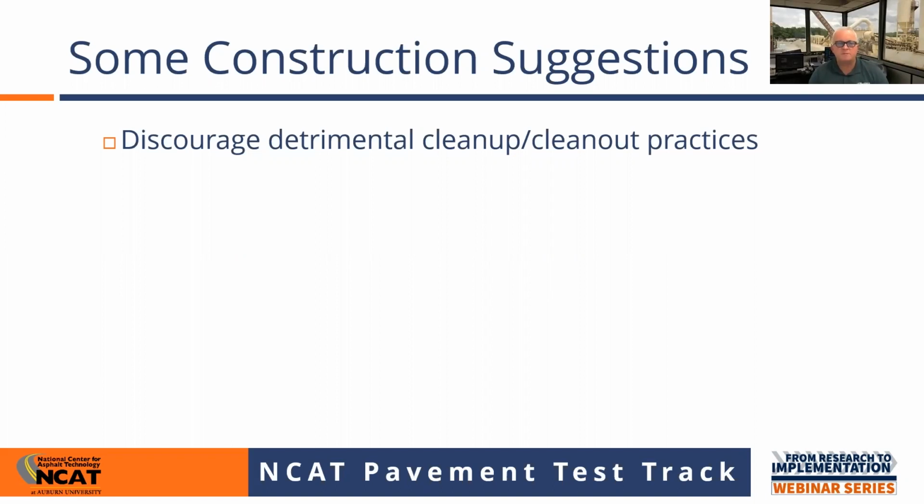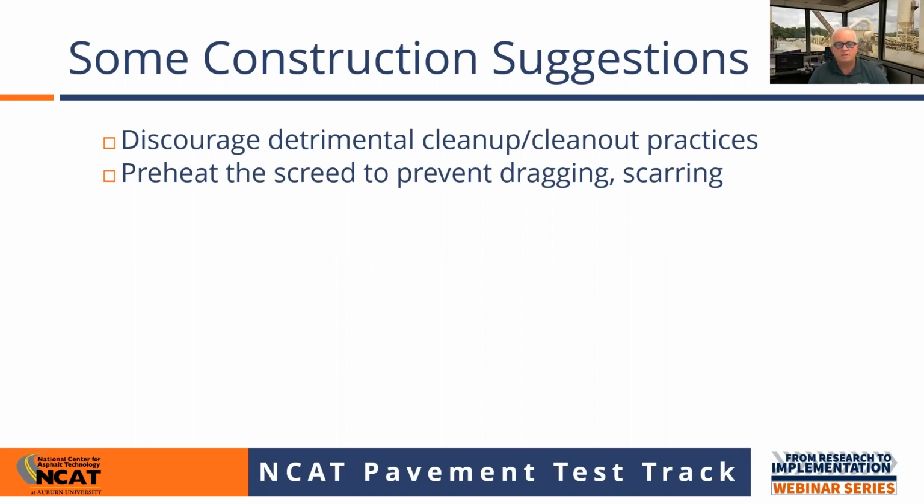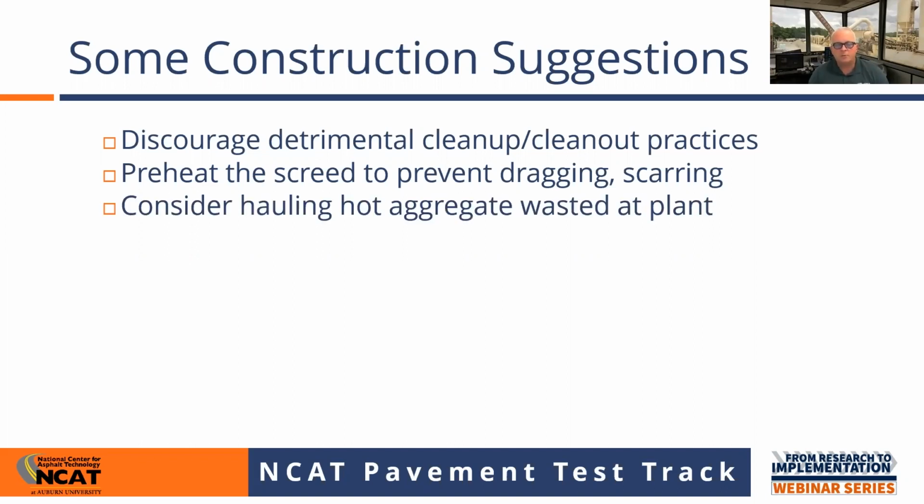Some of those products we use in the beds of our trucks. And I guess what I'm suggesting is that we use those same classes of products to clean our equipment up on the road to get ready for the next day. This is kind of the basics, but we can preheat the screed to prevent dragging and scarring. One of the areas where OGFC mixes tend to begin to fail first is at transverse joints where we pull off on new runs. So anything you can do to provide a really nice looking uniform mat when the screed pulls off, you're going to be better off, and you're going to get better performance. And preheating the screed can help.